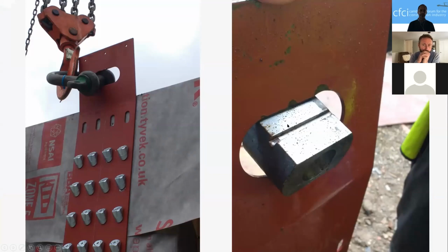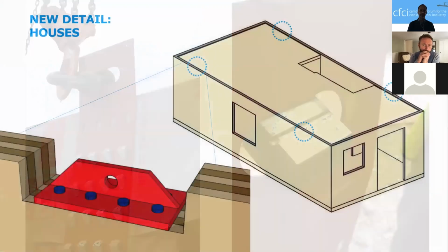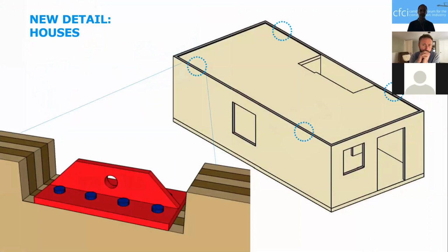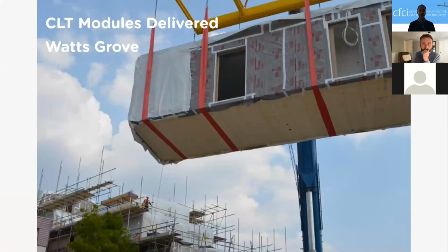So going back to evolving that design, and trying to make it really smart, we looked at whether we could change that, rather than a plate, into a reusable thing that's sitting down into the wall where the connection is. Or in the end, actually, you know what, we're not going to have the plates. We're going to strap it and then lift it from the underside. Because we have several straps, we can reduce the tensions and stresses around openings on the module.